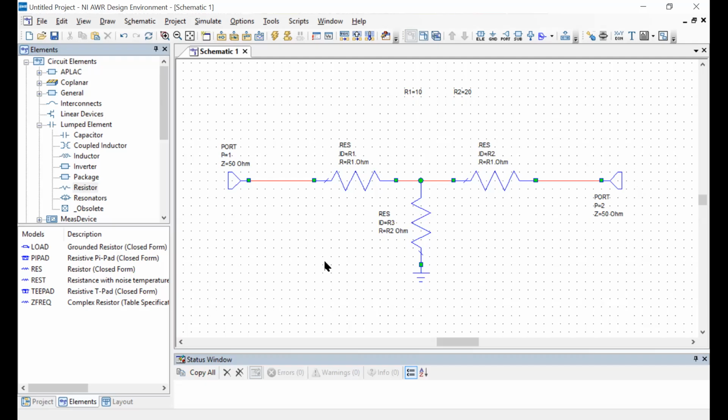It makes sense that this will function like an attenuator, because this looks like a voltage divider circuit, right? There is a voltage source, there is a resistor, and a second resistor to ground. So there's a current and there's a voltage drop across it. And now this terminal is picking up the voltage across the resistor here. So whatever the total voltage was here, the voltage picked up on this side is going to be smaller. This is of course a DC notion of a voltage divider, but that is the idea, right? You're trying to reduce the voltage or reduce the power going to the other side. So this sort of works.